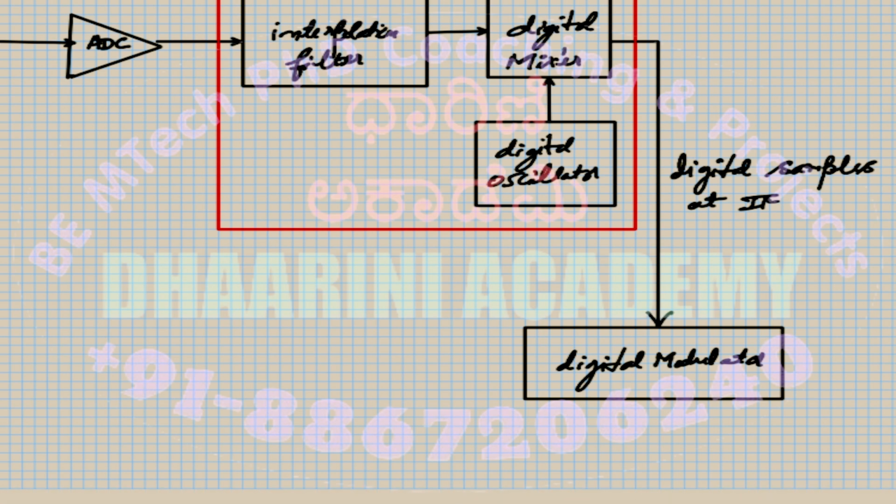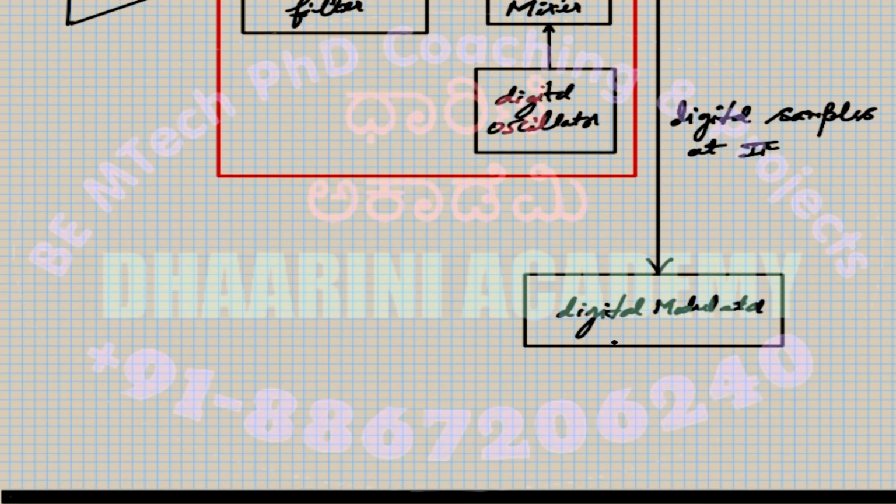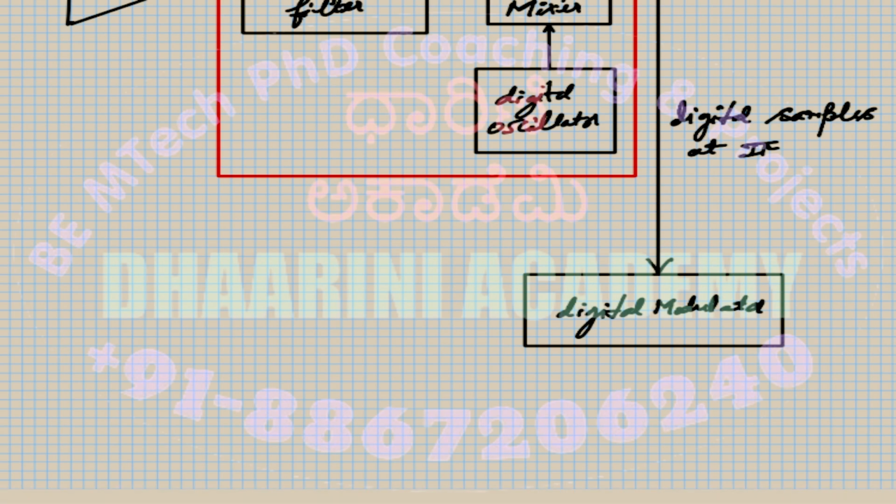Use any of the modulation techniques, right? We want the high frequency signal to be obtained at the output. Now, once you use this modulation, this is still in the digital domain. I want this to come back to analog so that you can transmit, right? Before the transmission, our expectation is that the signal comes back into the time domain, because the hardware which maps the signals and transmits them through the antenna expects analog, not the digital mode, right?